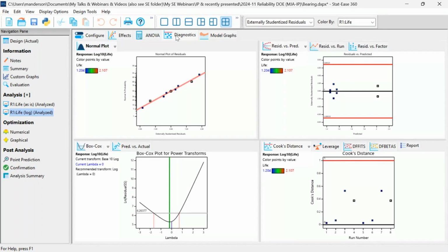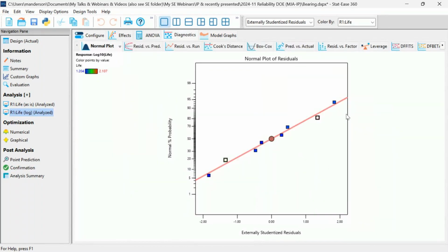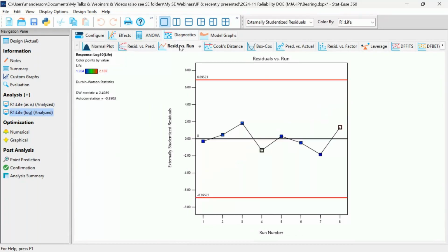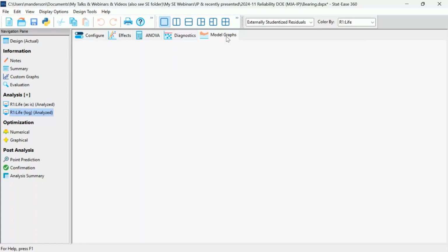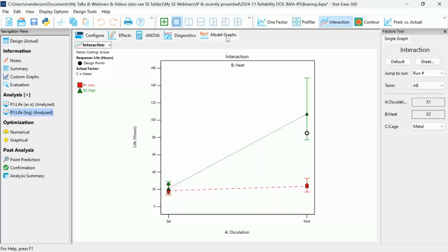We're now in the zone, and therefore we get a nice residual plot on the normal paper that falls on a straight line, via the fat pencil test. And the two apparent outliers now are well explained. And so this is kind of a cool example of how multi-factor testing, two-level factorial DOE, was applied as a reliability tool to accomplish their goal for increasing the life by double.